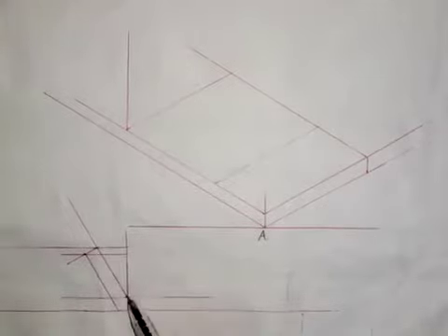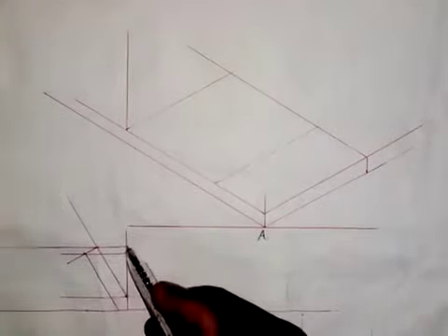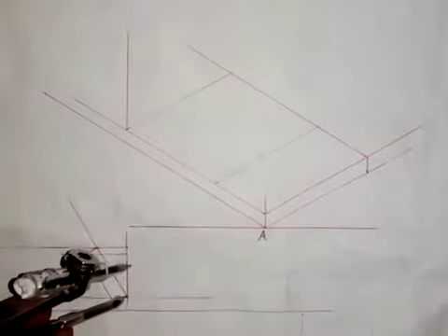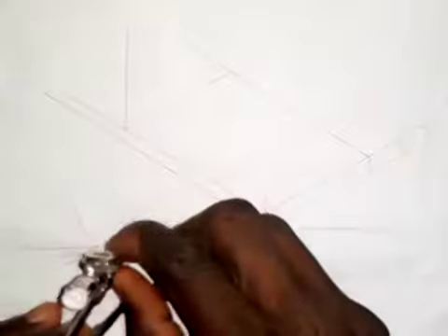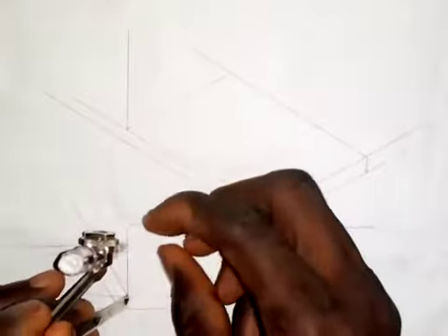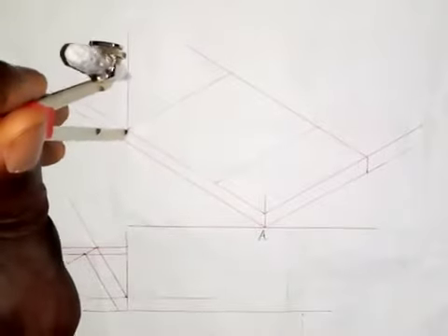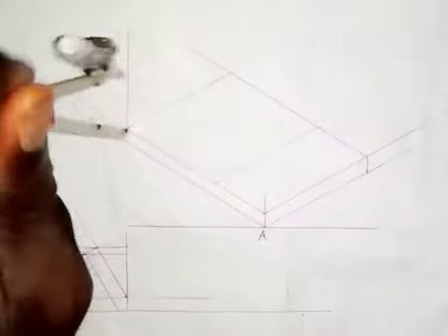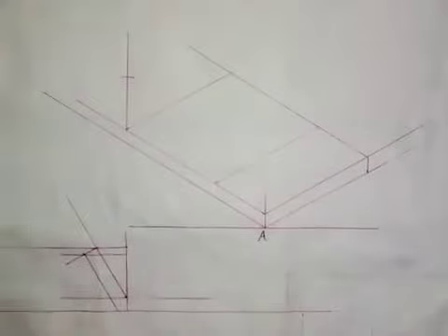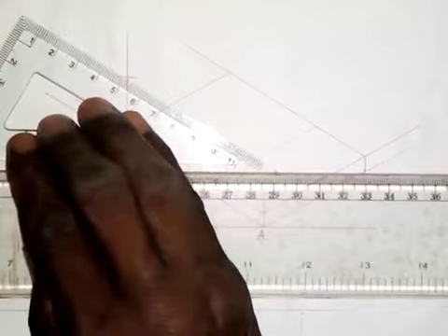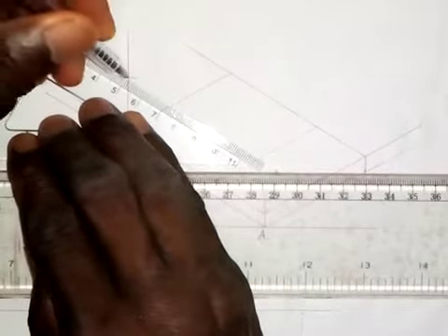So what you need to do is to take a distance from this point to this point. So then we'll be able to bring out this point. So what I mean is this: put the pinpoint of the compass here, extend it to this point here. So take this distance, bring it to this point, put a pinpoint at this point, and draw an arc here, like this. So with this arc that I've drawn, I will take my 30-degree set square. So take it like this. Okay, then I will draw this line in this direction.